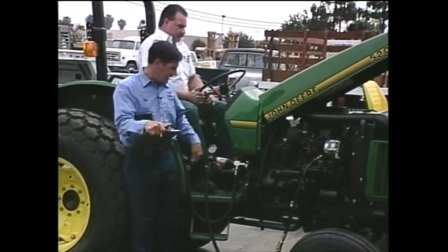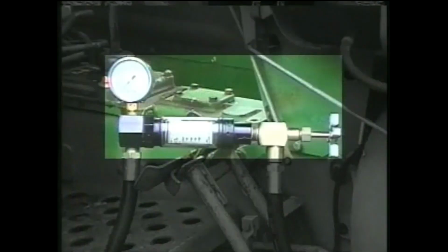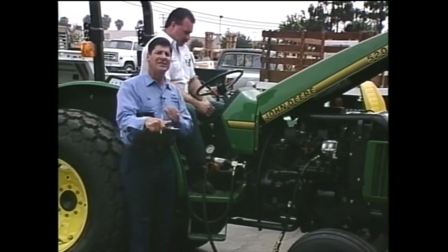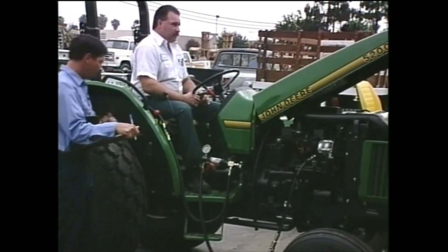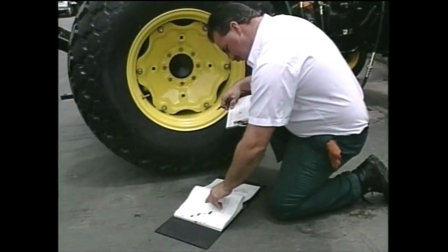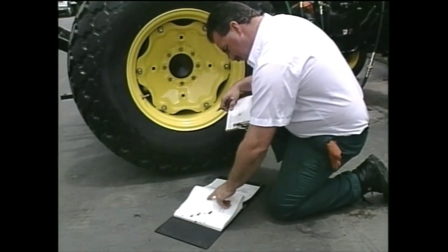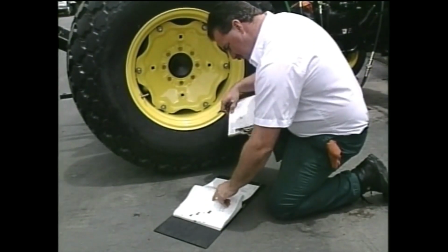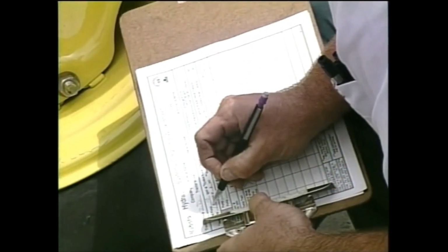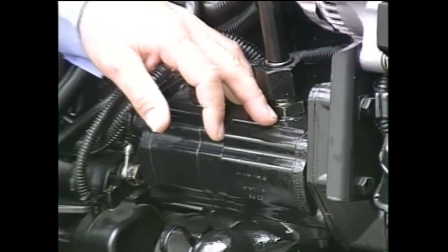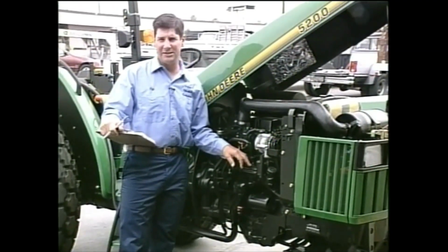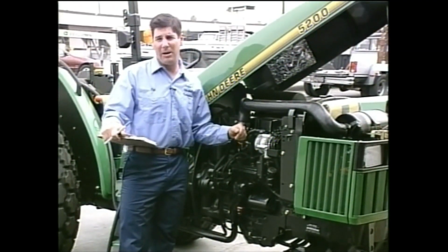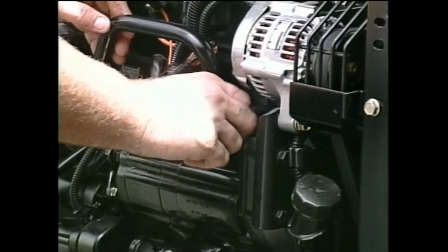Pumps can be accurately tested with a flow and pressure analyzer like this one. This type of testing is necessary for high-performance machinery. Look up the system's operating pressure and the pump's flow in gallons per minute. After the engine is warmed up, shut it down. Pumps must always be totally isolated from the rest of the system before they are tested. Anything downstream of the pump could cause it to look faulty.